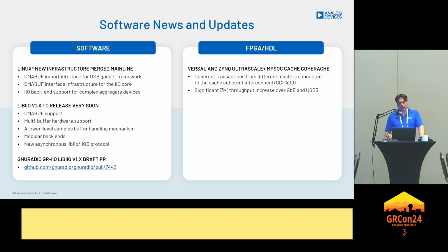We also added I/O backend support for complex aggregate devices. Those are typically converter devices where you have two interfaces: one to configure the converter, typically a SPI or I2C interface, and then a data interface. The data interface is abstracted by an AXI core that is a platform device. You always had the problem of a SPI device and a platform device, and how do they communicate and interact with each other.